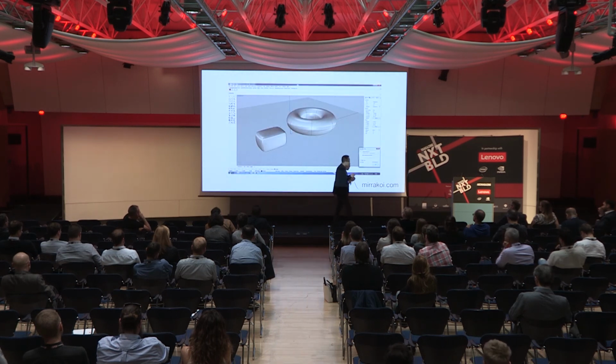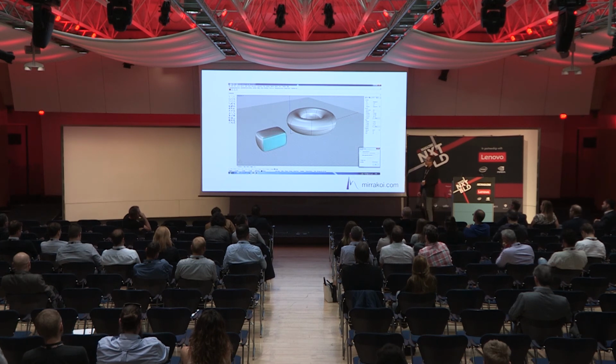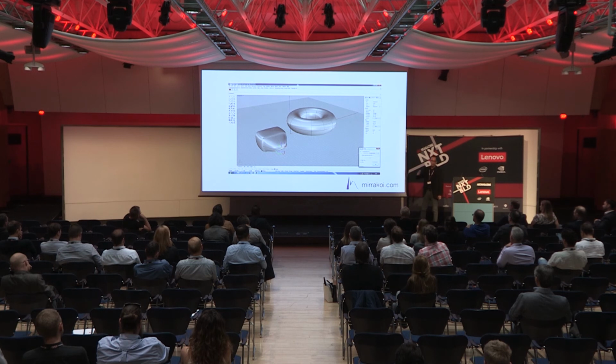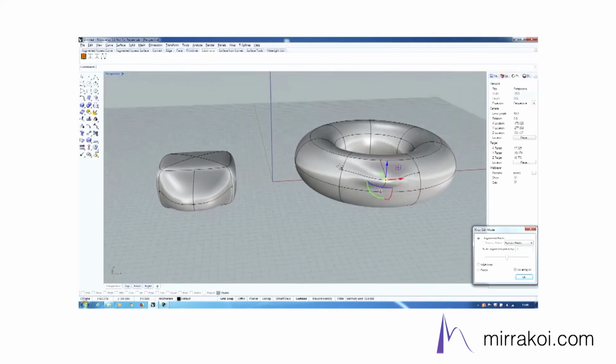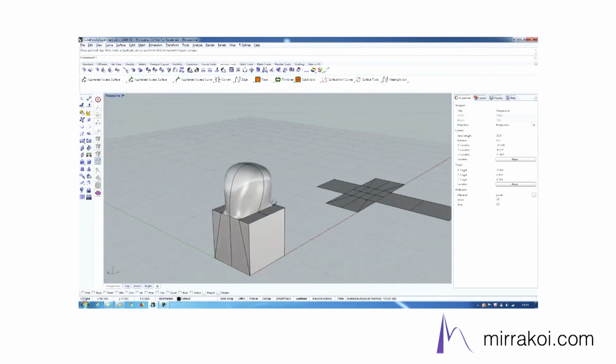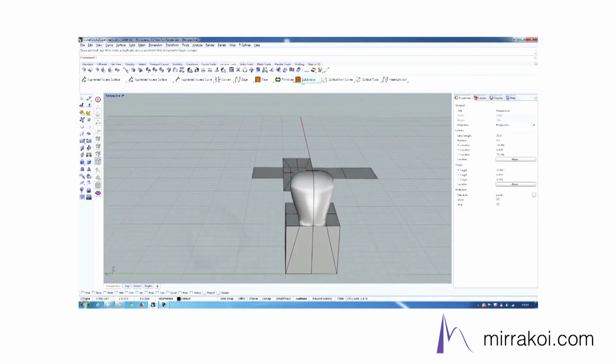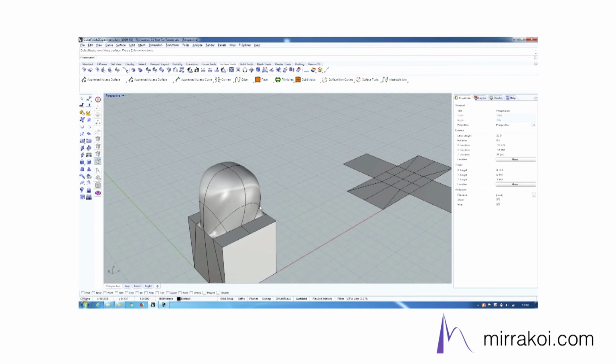Subdivision and local refinement. This is actually subdivision compatible. We have our own native Xyros subdivision algorithm. This is especially useful if you do local refinement, if you want to add certain details to the object, to the surface, or to the volume. You can just introduce a new control point. Again, the new control point keeps all the characteristics of any other control point, so again you have access to higher order derivatives, curvature, and so on. This is again really simple and supposed to be intuitive.